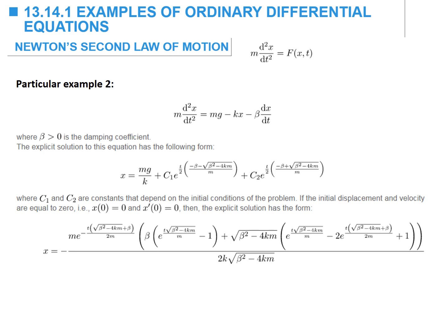You can also add damping to the equation. Damping is usually added by a term that's directly proportional to the velocity. This equation says that one of the forces acting on the mass is equal to negative a constant multiplied by the velocity, which basically says the higher the velocity, the higher the damping.